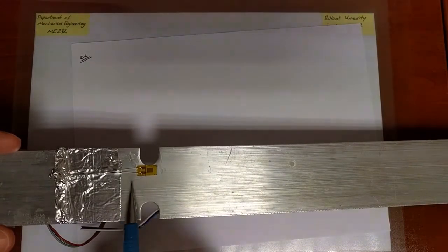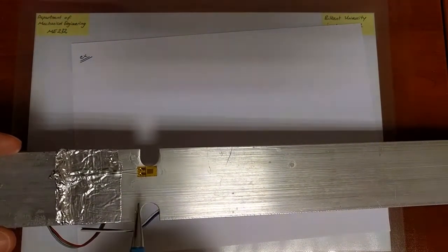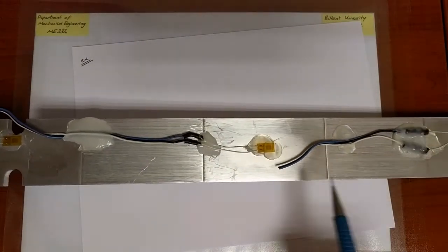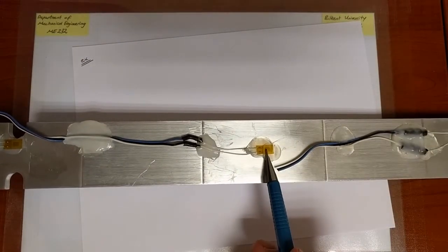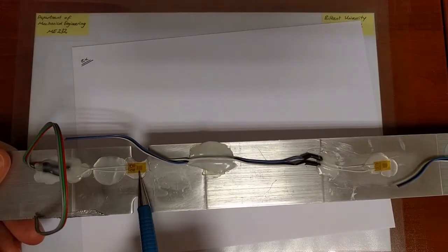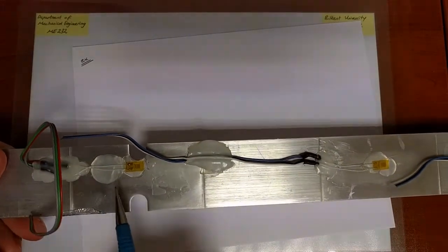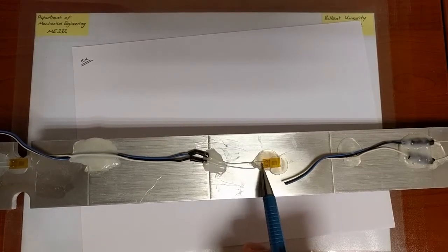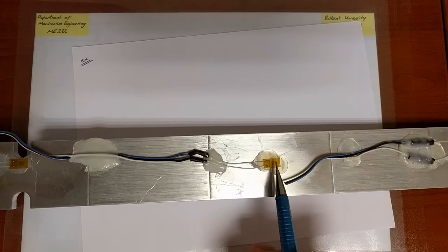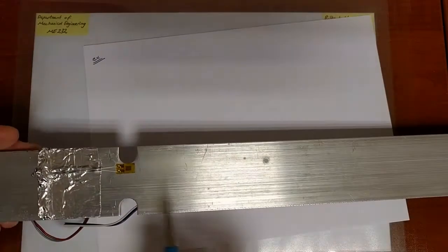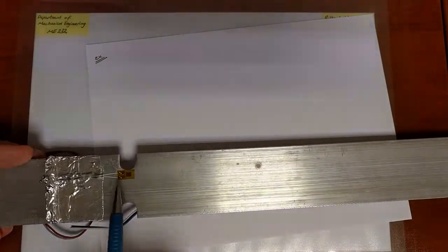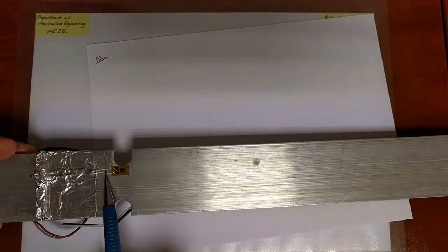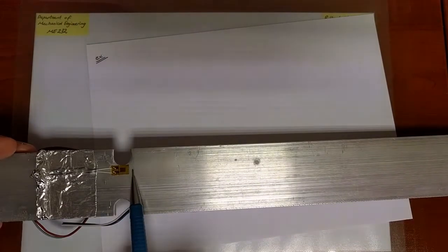This device is called a strain gauge, and you can put several of them at various locations throughout a structure to monitor the state of strain at, for instance, a point where you expect some stress concentration. Now, one thing to notice is that the strain gauge always has a certain axis. What the strain gauge is measuring is the strain, which is first of all normal, and the direction of that normal strain is along that direction.